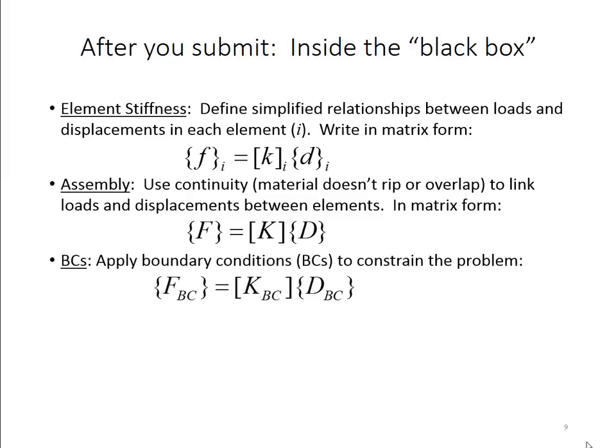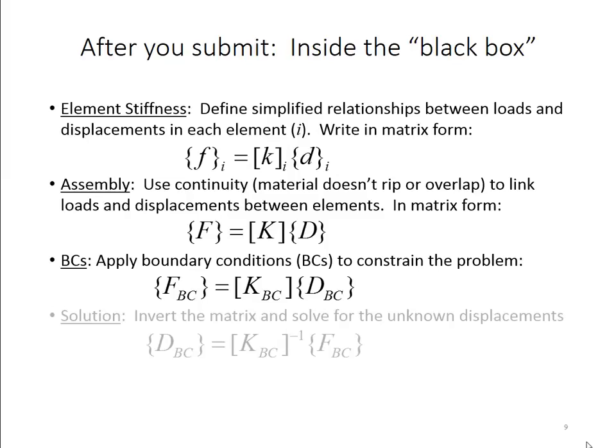Then you apply some boundary conditions, so you specify what points are actually known displacements. When you do that, for computational reasons, we actually modify the stiffness matrix, the displacement vector, and the force vector, putting the BC for boundary conditions in each of them. We'll talk about this later on in the video series.